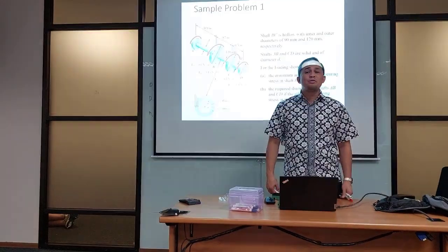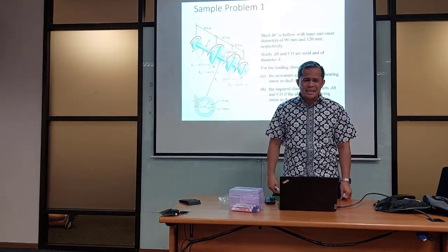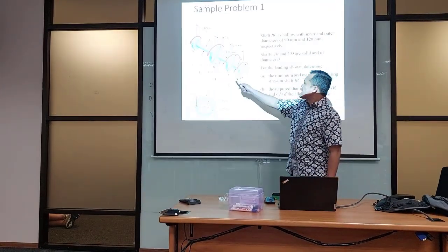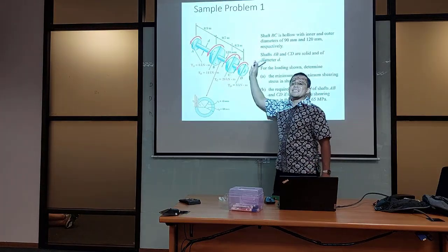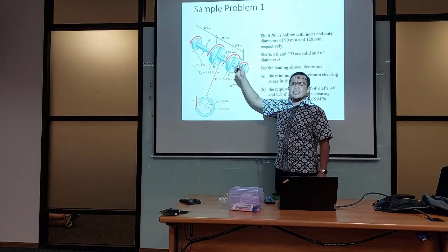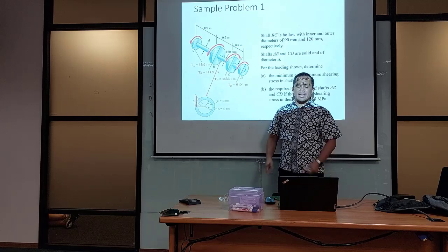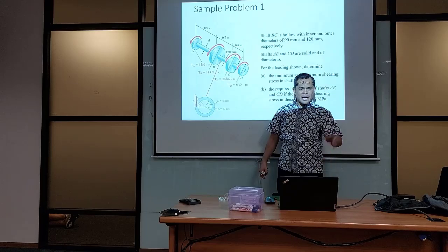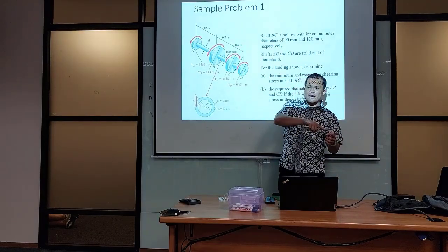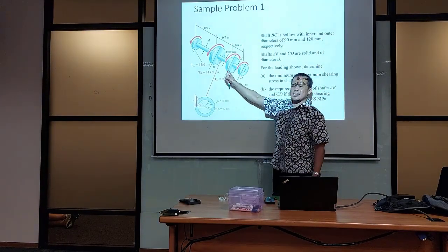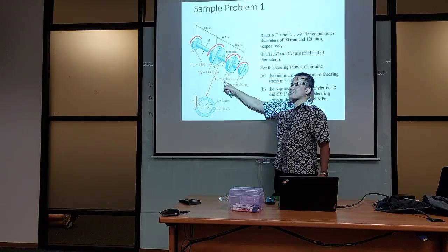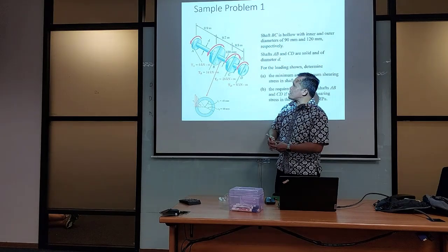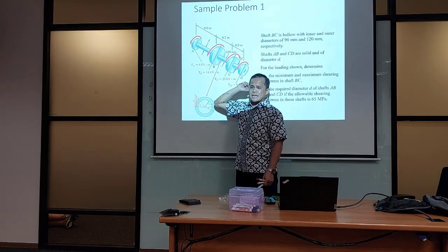Let me change to pulley. C. C is the place where you locate the engine connected with a pulley, for example. So the engine is rotating. It is connected with pulley C, applying 26 kilonewton meters. That 26 is used to rotate A, B, and D.